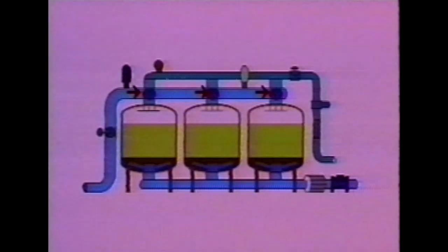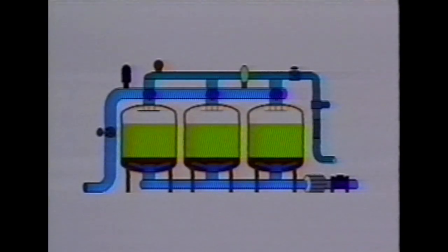The backflush hardware starts with a 3-way valve. It either lets dirty water into the tank from the inlet manifold or stops that flow and opens a connection between the tank and the backflush manifold. Other necessary hardware includes air vents and pressure relief valves, backflush adjustment valves and piping, and other devices mentioned later.